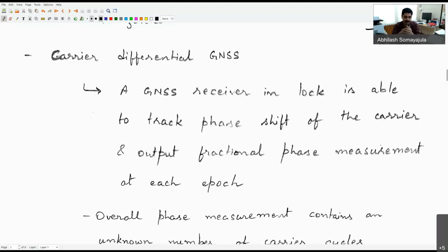But here, because of the disturbances, you will see that the phase itself might change with time. When that change in phase is detected, you're using that additional information to figure out how much I have moved. And that measurement is much more precise because you're now looking within certain wavelengths of that carrier frequency, trying to estimate how much phase difference has come through.